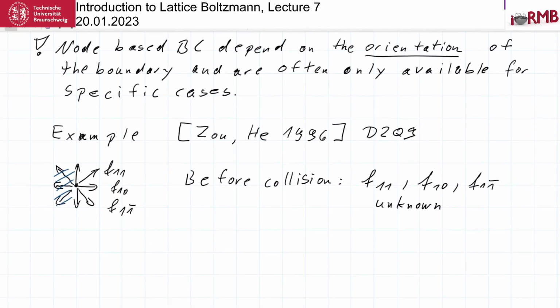at this boundary we want to specify both density and velocity, and you immediately notice that this is a little bit different from the Navier-Stokes equation. So they would probably say, hey, wait a minute, I want to specify either a velocity boundary or a pressure boundary. This is a velocity and a pressure boundary, okay? So a little bit specific here, but this is the way it is.